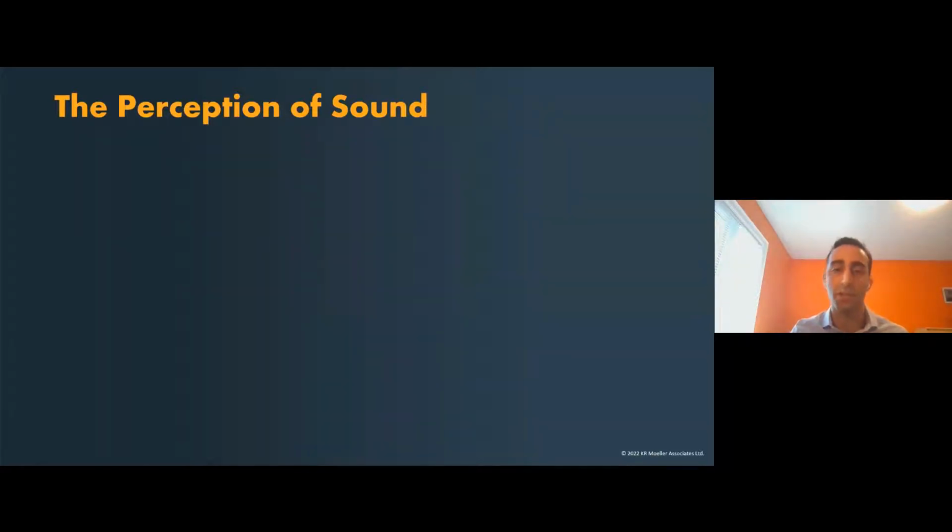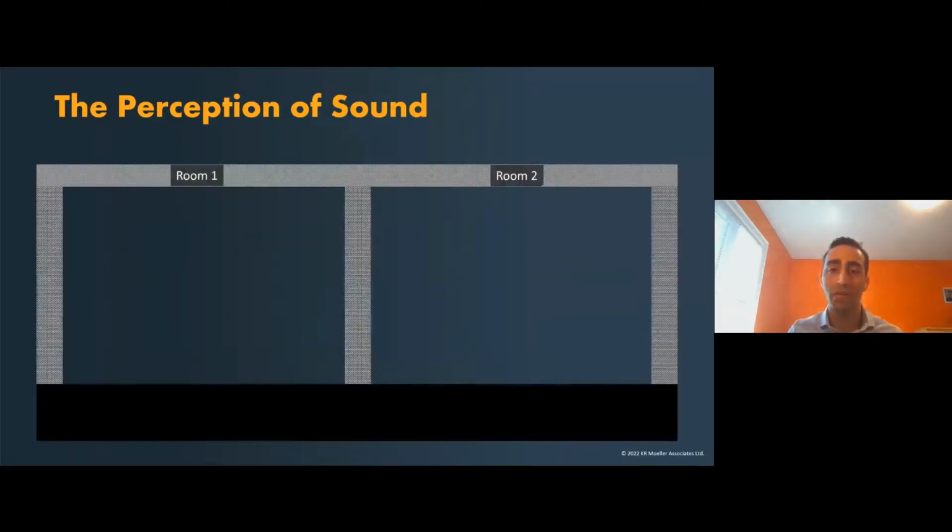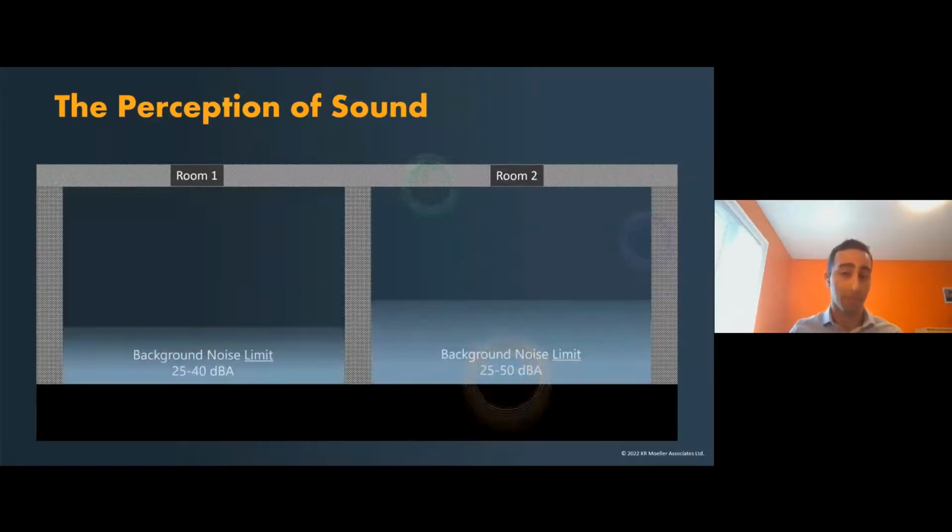However, the adaptation of speech privacy theory in the built environment is a little bit more complex, but the following nuances are important to understand if we want to develop the notion of acoustical equity. Here we define an environment separated in two spaces by a partition. The first step is to consider the ambient sources, that is, the acoustic energy that actually exists in the space that is generated from building-related systems, services like heating, ventilation, and air conditioning systems, or HVAC, and mechanical, electrical, and plumbing, or MEP.